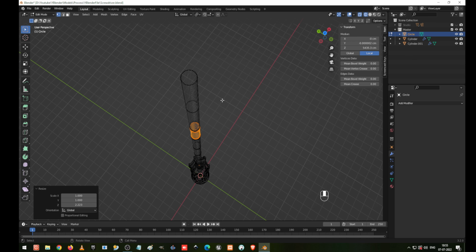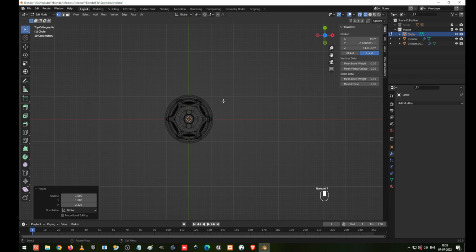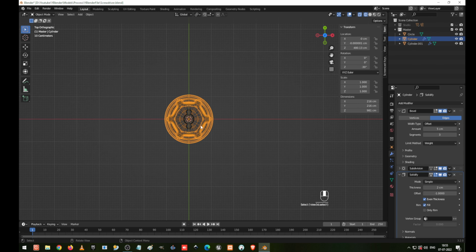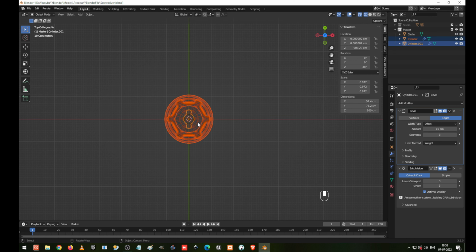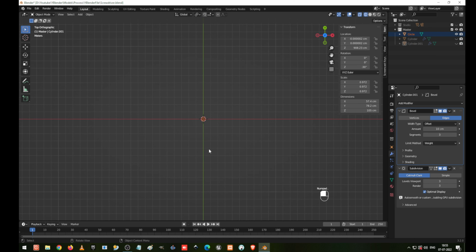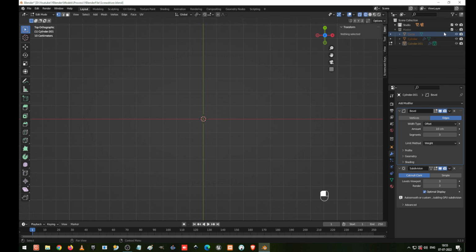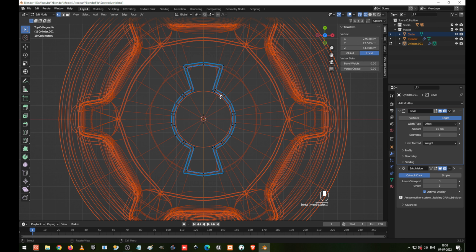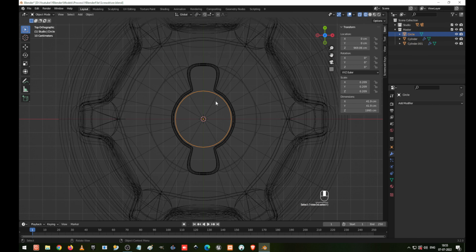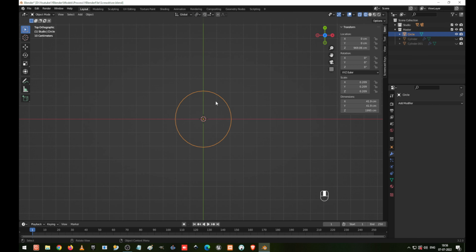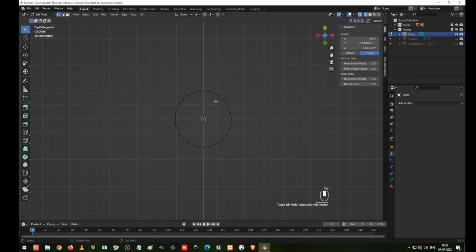And for this one I'm going to do the mirroring now, so it will be very easy to do the modeling. Go to the top view using the 7 key, and I go to object mode. First I select these two and press H to hide, and select this. I zoom in, go to edit mode, Alt H. Okay, this master one is good to hide. Now I select this, Shift H, and unhide the others. Now go to edit mode.